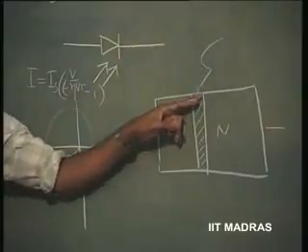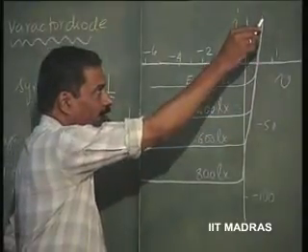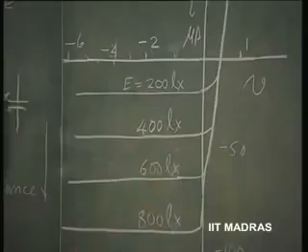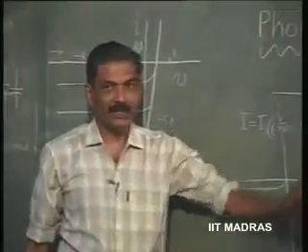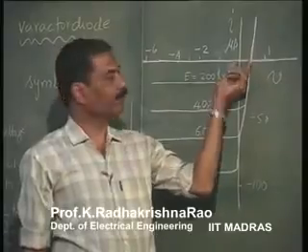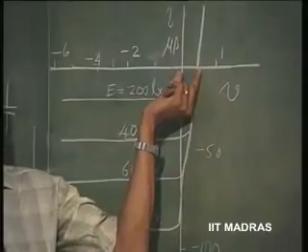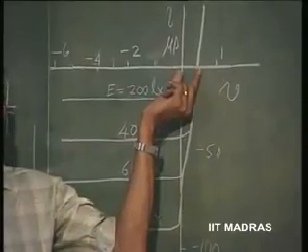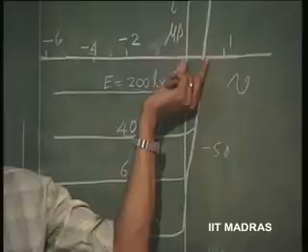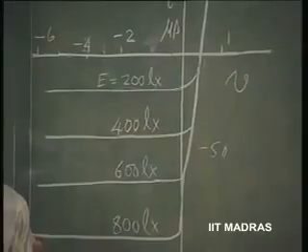So, this is the source from which it gets the energy. So, this particular diode characteristic now will be like this. This is the reverse saturation current saturating here. Not only that, because it can be sustained like this, it is going to have an open circuit voltage, because this current is 0. This open circuit voltage if the intensity is large enough, gradually goes towards the 0.5 value for silicon. So, this is the open circuit voltage, and therefore, it can be used as a voltage source, a battery.